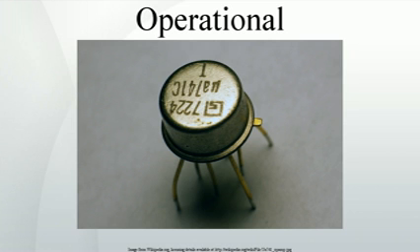1961, a varactor bridge op-amp. There have been many different directions taken in op-amp design. Varactor bridge op-amps started to be produced in the early 1960s. They were designed to have extremely small input current and are still amongst the best op-amps available in terms of common mode rejection, with the ability to correctly deal with hundreds of volts at their inputs.